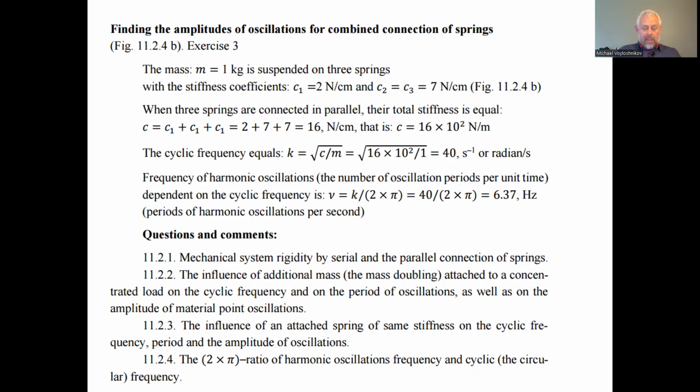Exactly, the oscillation period increases in the same proportion. But if we suspend the load on springs connected in parallel, the frequency increases, because the stiffness of the total suspension is equal to the total of the stiffnesses of the springs in the parallel suspension. The frequency increases in proportion to the square root of the increase of stiffness of the parallel suspension of springs.